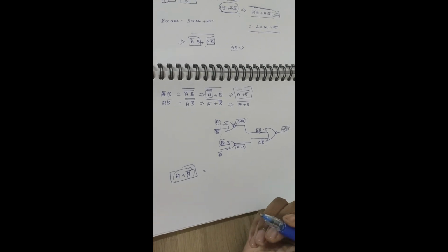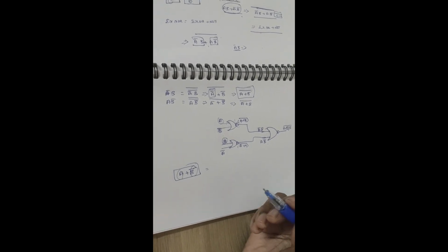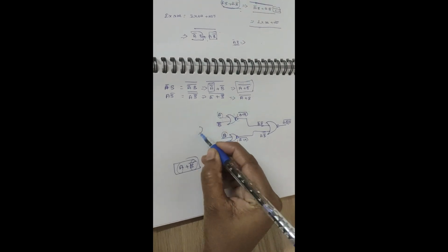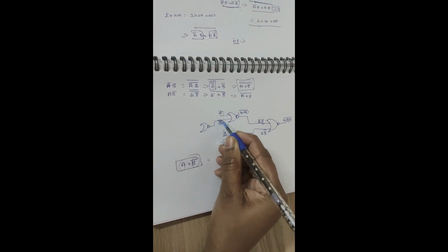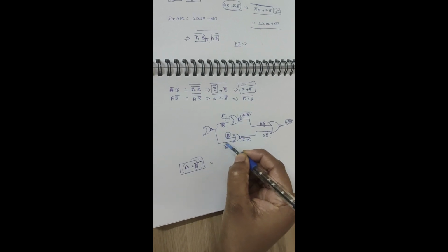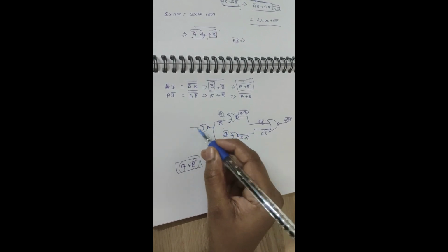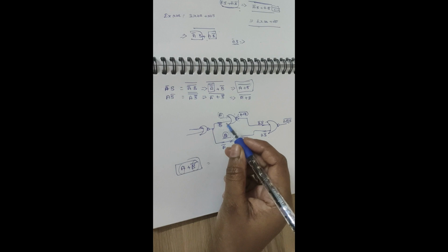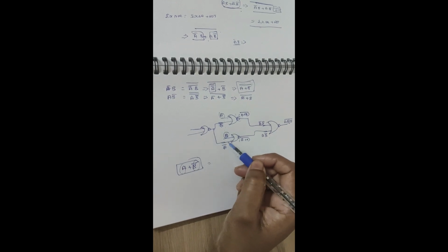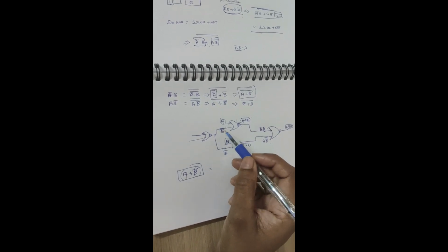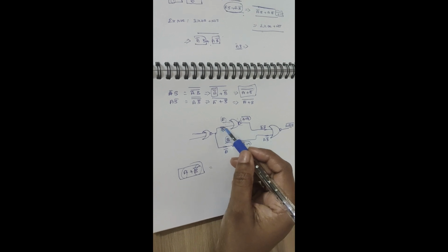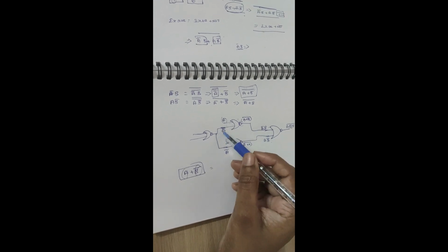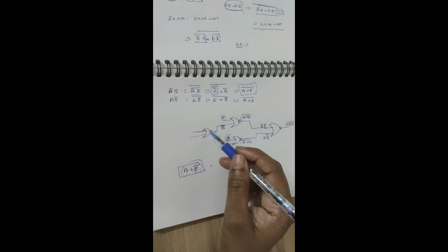That will be with only one NOR gate, and that will output here and here, and it won't make any other things. Because if we had done it like this, it would be one more gate; this is the reduced gate version.